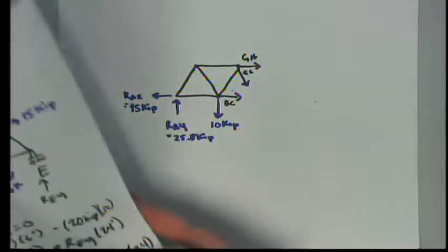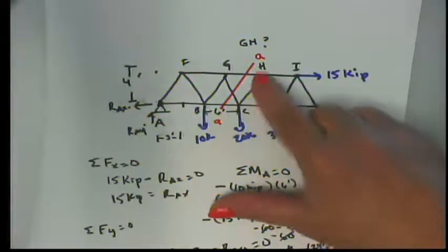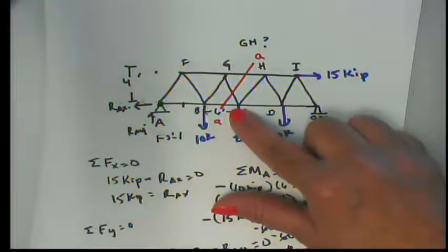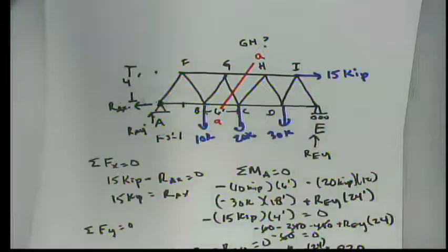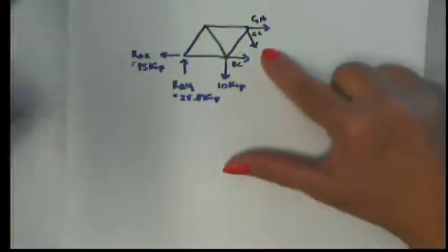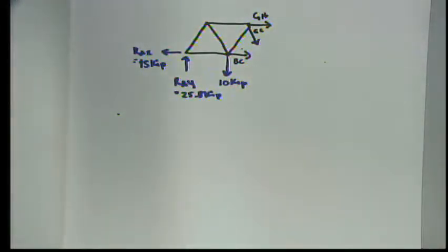If you look at this line that I've cut, and I would just refer to this as a cutaway, I've drawn it straight. That's pretty arbitrary. The only thing is it has to cut through the entire truss. You have to be able to split the truss into 2 pieces, and everything that's cut becomes a force in your section diagram. All right, so let's take a look here. So you can cut it any way you want. Yes, you could cut it any way.